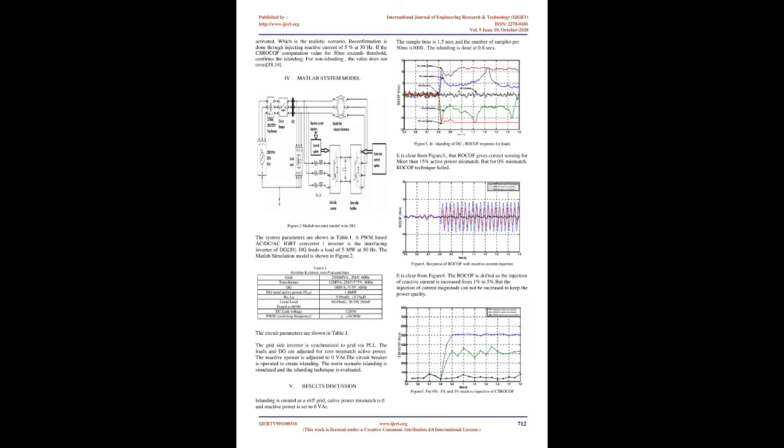24. A special controller is proposed, which detects both positive and negative sequence components during unbalanced faults 23. A remarkable work is done by focusing on stability during grid mode only. The modeling was done in PSCAD/EMTP platform 25.